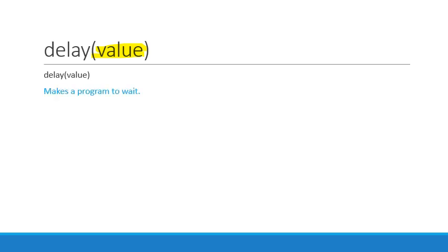For instance, in my void loop function, we are going to firstly use the digitalWrite function. Just picture it with me. I know it may be difficult for now. We use digitalWrite to set my LED pin as HIGH, to turn it on. Then we use the delay function to make it wait for a second. After that, we turn it off with digitalWrite, and use the delay function to make it wait for another second. That is what we'll be doing with the programming.